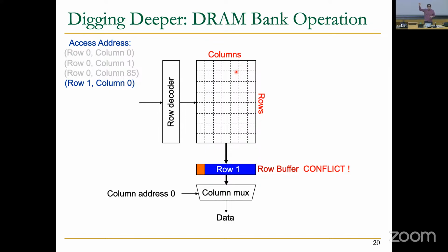That will bring the data to the sense amplifiers. Because of how the memory array operates, which we will get to in upcoming slides in more detail, the moment you bring data to the sense amplifiers, you've also restored the charge in the capacitors of the row. So by accessing a row, you have essentially refreshed it.